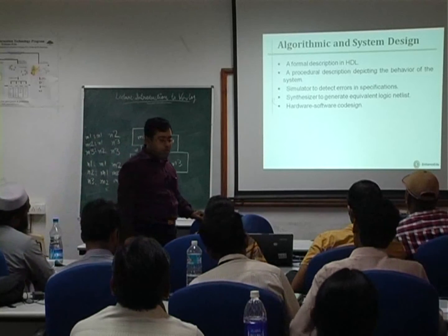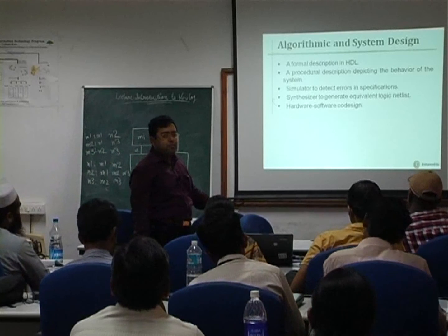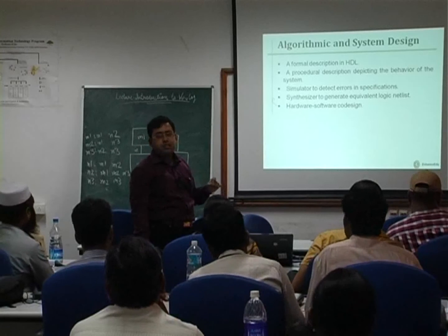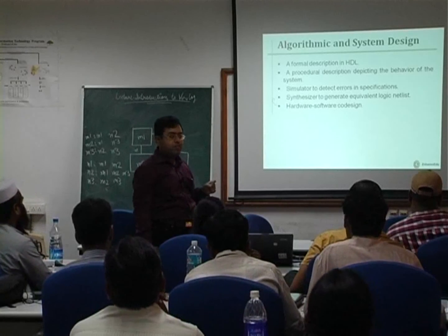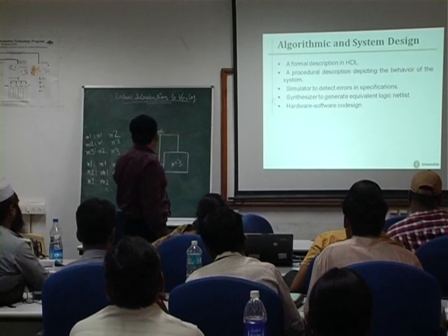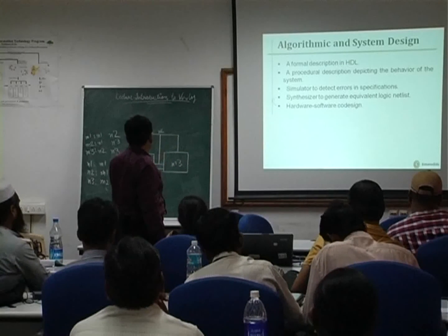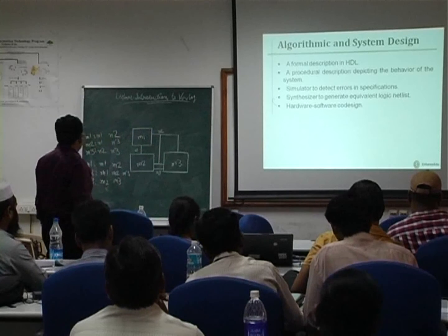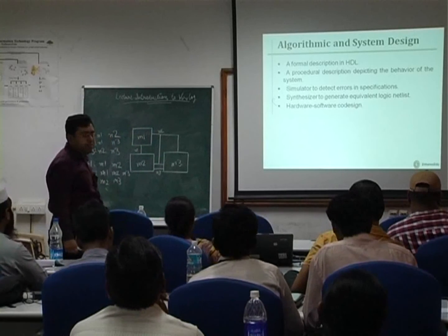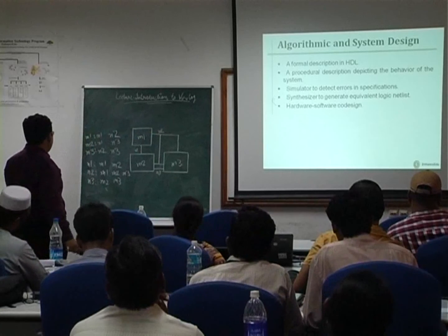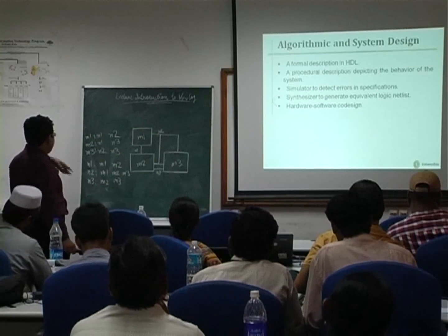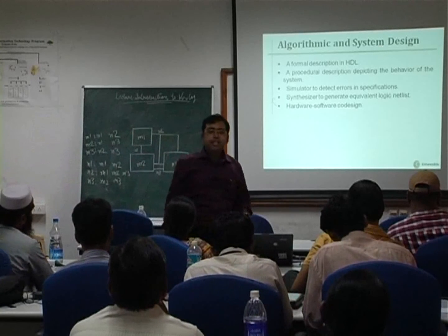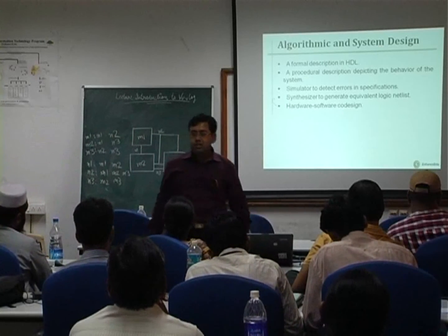So this list of modules or nets that depicts the interconnection of the components in a circuit, that is called a netlist. In the former case, in which we list up the modules and then find out the nets connected to the individual modules, that type of netlist is called a module oriented netlist. And the latter case, when we list up the nets and find out the modules connected to the individual nets, that type of netlist is called a net oriented netlist.